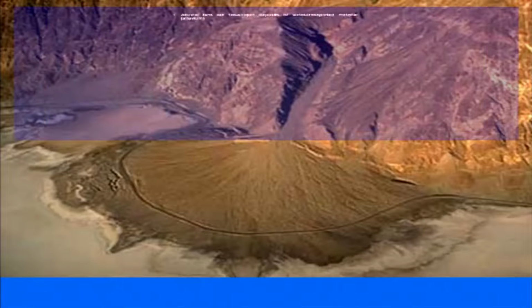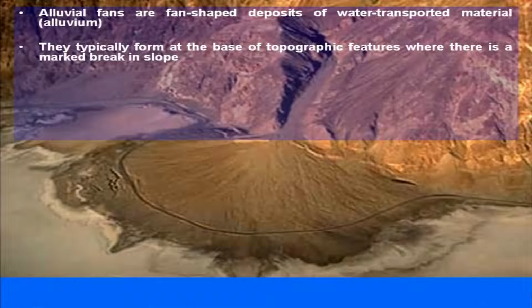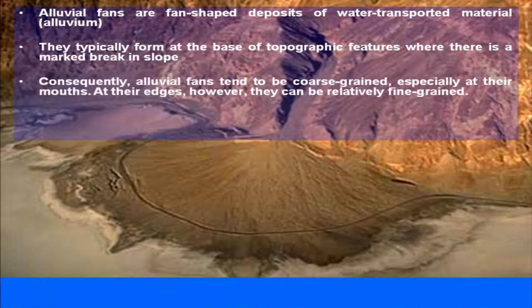So, further, alluvial fans are fan-shaped deposits of water-transported material or alluvium. They typically form at the base of a topographic break or topographic feature, where there is a marked break in slope from steep to shallower. Consequently, alluvial fans tend to be coarse grained, especially at their mouth, that is the proximal part, and at their edges. However, they can be relatively fine grained. So, close to the mouth, the proximal part, they have the coarser deposits, and as you move further downstream at the edges, you will have finer deposits.